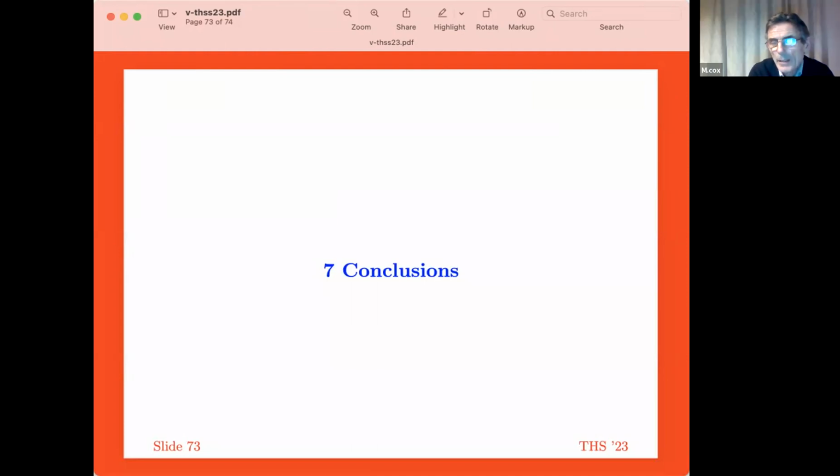Yes, most likely. But in my experience, once you get down to model scales, it's difficult to find a flexible reinforced fabric of a scale thickness. You either lose the scale similarity on the thickness or you lose it in the stiffness. Yes, you're 100% right.